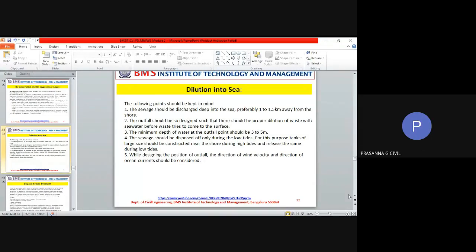Only sea? Can I make it a statement that dilution can be done only in sea? No, ma'am. In any water body. Understood? Are you able to hear me? Yes, ma'am. So I want to put it into a water body. What all things should I consider? Ma'am, it should be discharged deep into the sea, preferably 1 to 1.5 kilometers away from the shore, ma'am.